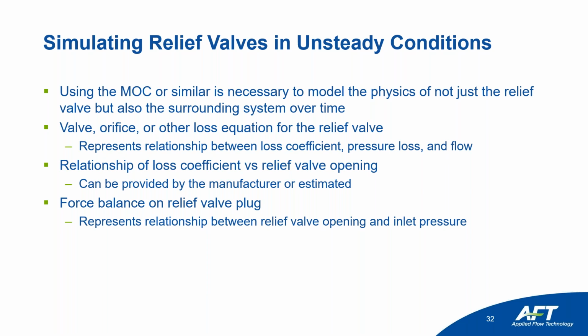So modeling a relief valve usually is done with some kind of a loss equation. It could be your loss coefficient, CV, KV, or if you can get performance curves, lift performance curves, or loss coefficient versus relief valve opening characteristics provided by a manufacturer, or if you could attempt to estimate them, usually those are going to be your best bet for using a one-dimensional simulation like AFT Impulse.